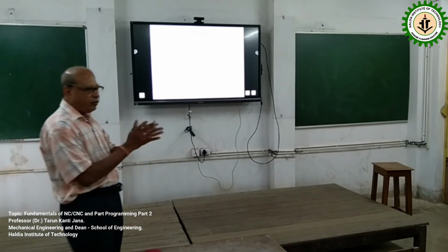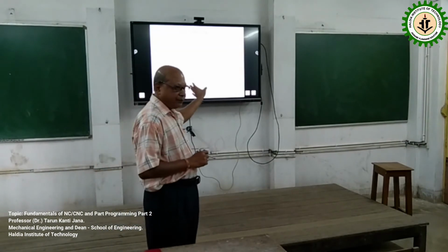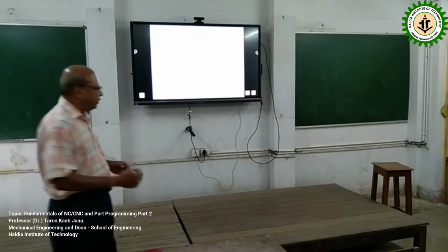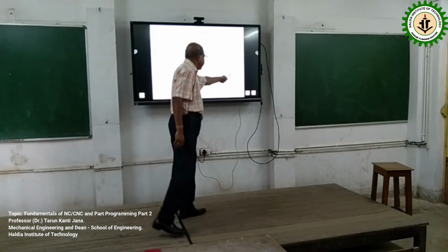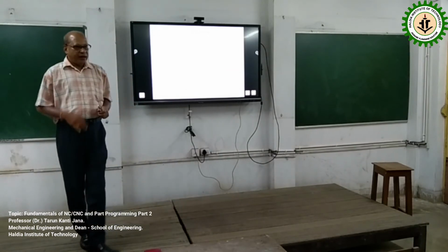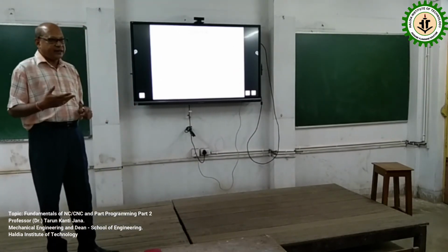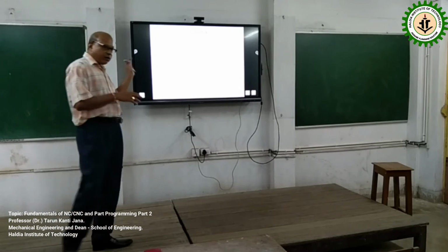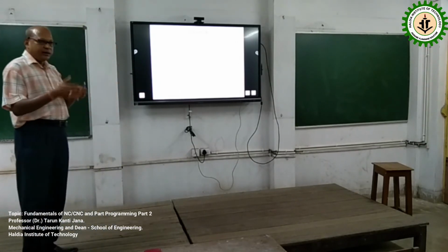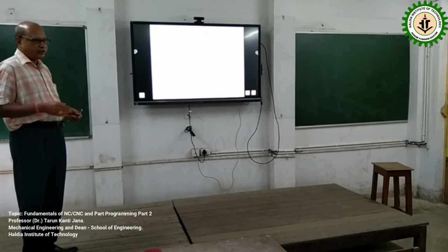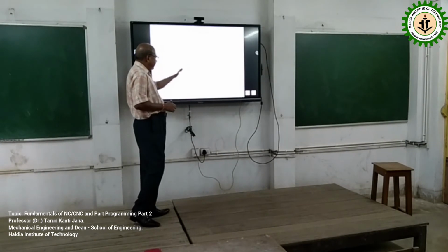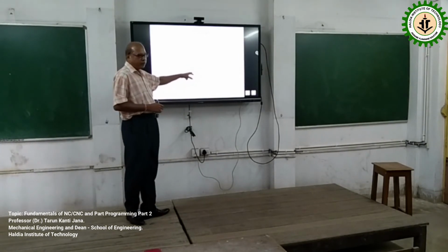So that value will be stored in the positive counter, and the instantaneous value or actual value as measured by the position sensor will be fetched back to the negative counter. This actual value will always keep on changing, and based on that, the comparator will calculate the error signal, that is, the reference minus actual.